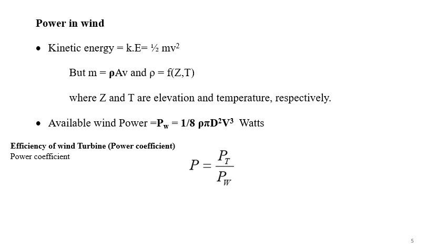However, the velocity is increased for a given value of the free wind speed, that is the air density. Okay, so pressure drop increases at first and passes through a maximum and then decreases. Okay, hence for the specified free wind speed, there is a maximum value of rotor speed. So the fraction of the free flow wind power that can be extracted by the rotor is called the power coefficient.